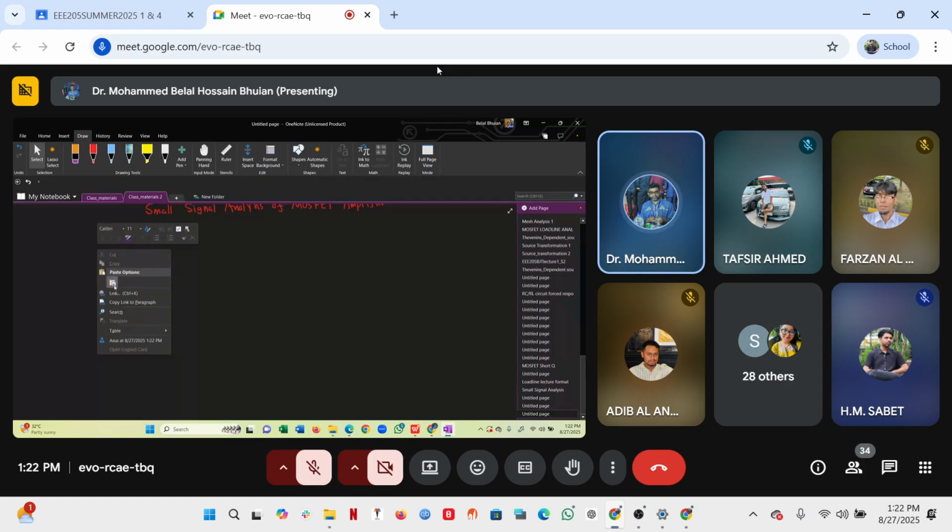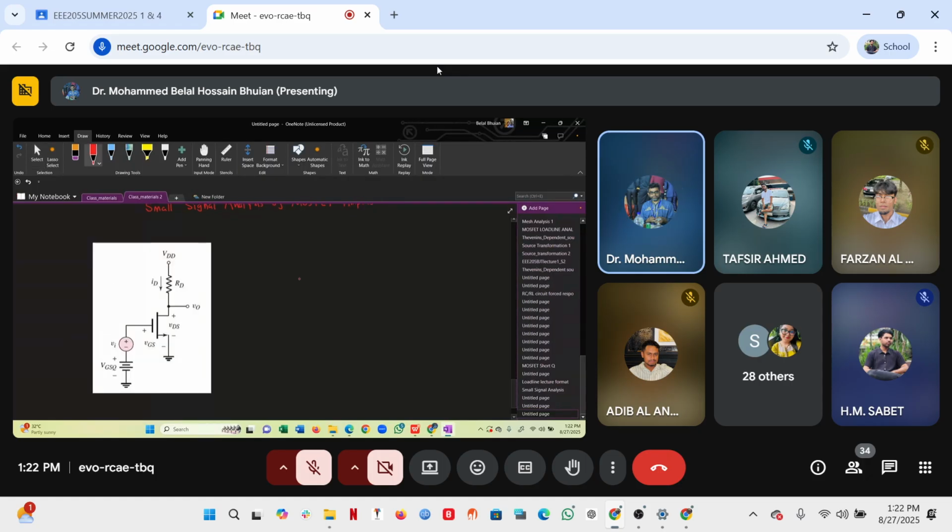Okay, so that is our hypothetical amplifier consisting of a MOSFET. What do you have? A biasing VGS, and then VI, the signal that we want to amplify, and VO is where we take our output. So that's called common source configuration, right? Okay, again, we have both the DC signal and AC signal present. So the way we're going to represent the same thing is that all capital represents large signal, all small represents small signal, and the mixed case represents the instantaneous signal.